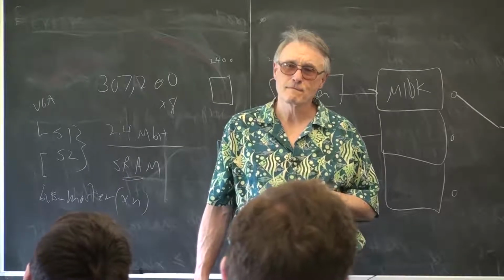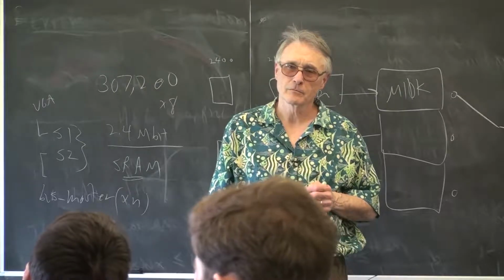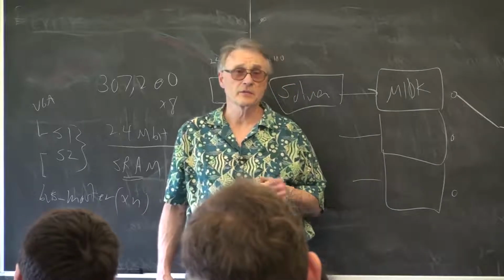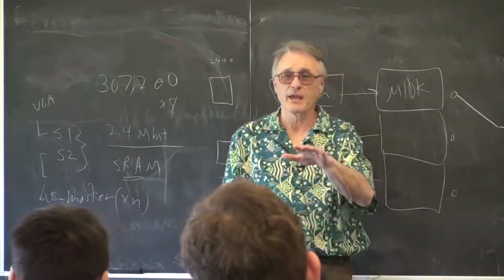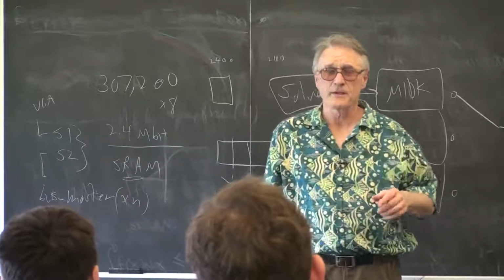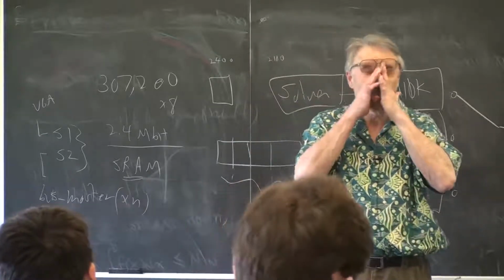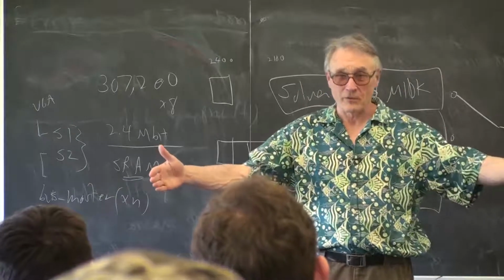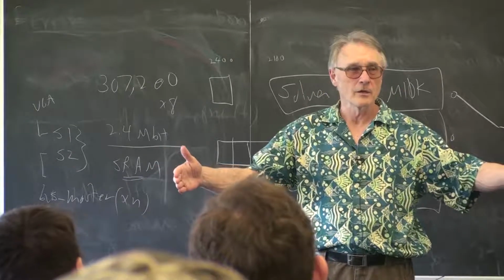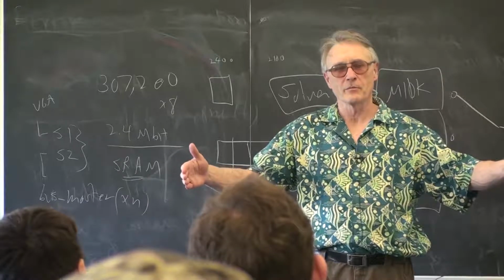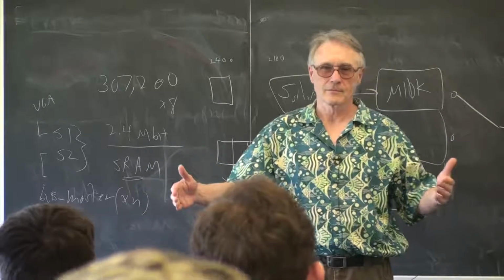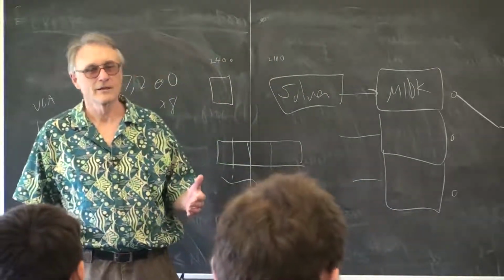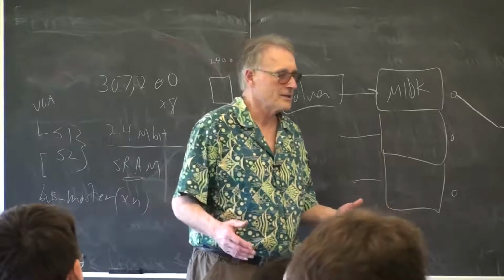There's also a thing you can do where you put a PLL on the pin and then modulate the PLL. That would work too if you had good control over the PLL. These tend to be integer PLLs, so you can't quite do it with enough accuracy. But yes, that is also illegal because now you're broadcasting at 20 different frequencies, 4 megahertz apart. The first one happens to be in the middle of the marine distress band. So that's a bad thing. Don't do that. Figure out another way of broadcasting if you're going to do that.